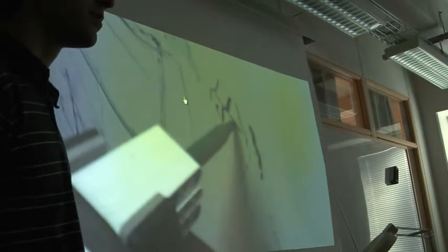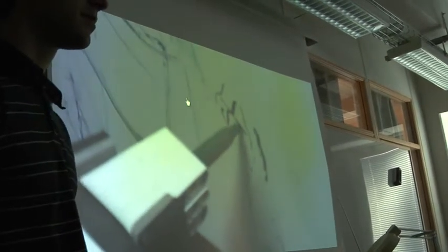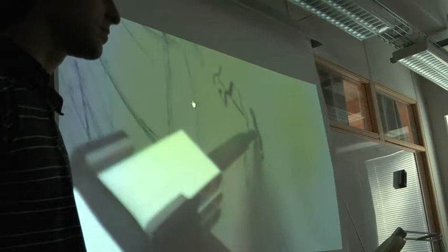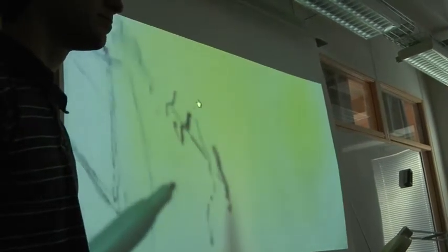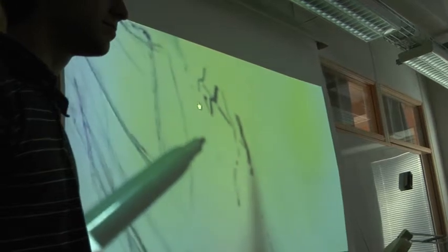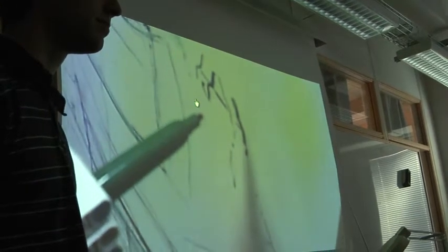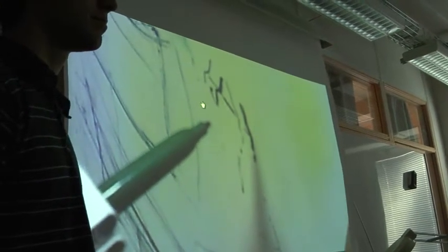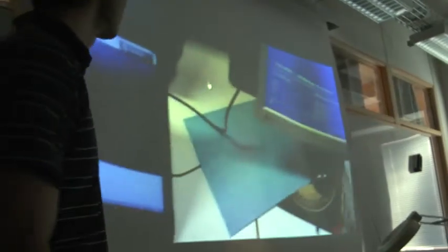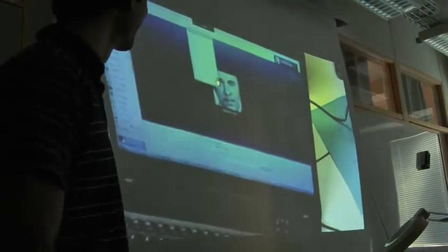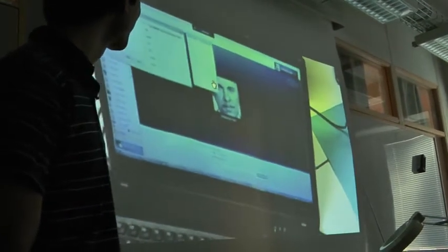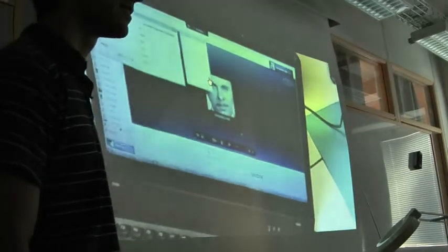Because of this forearm, for any motion of drawing A or B, both this motor and this motor have to work simultaneously. The placement of the motors is such that I cannot go all the way through because of the motor here. It's basically as if someone put a pillar here, so I cannot do this completely. This motor is also obstructed. So because of this, we cannot reach every single point in the plane.